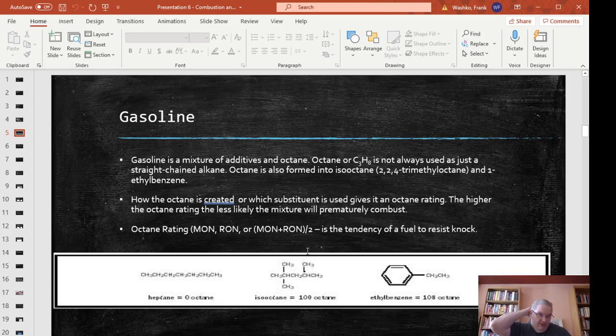So if you have an engine that has a high spark advance for performance and has a high compression ratio for either performance or efficiency, that's why you would say, well, you have to run high octane fuel in here, because we need a fuel that resists the urge to burn or self combust and create a whole knock problem, and that kind of thing. So with a higher octane fuel or an engine that's designed for a higher octane fuel, you're either going to get more performance out of it or you're going to get higher efficiency out of it, possibly both or one or the other.